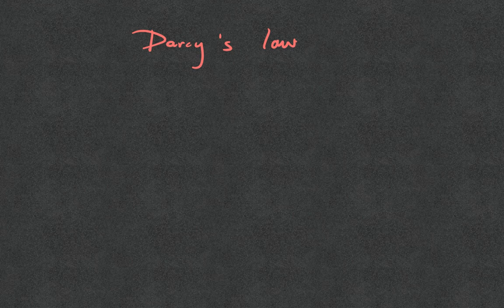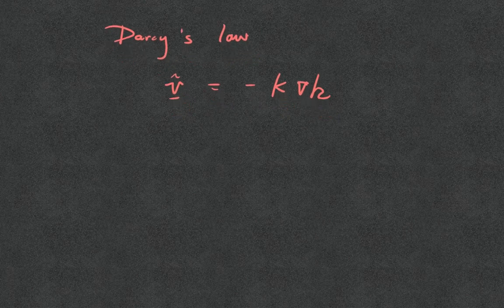Okay, so just go back to the previous equations. I have the Darcy's velocity that is equal to minus k gradient of h. Okay, so this is our assumption. I'm sorry, there's a dot here. Okay, what should the k look like? k could be a scalar. In this case, I write k as a scalar.